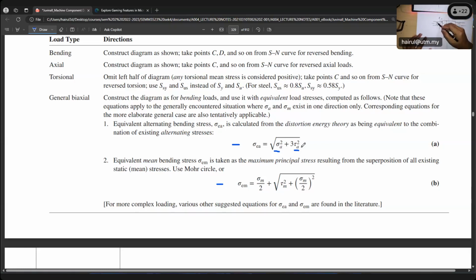Here we have a groove. What is the purpose of the groove? And what is the purpose of the shoulder? When you mount a pulley, can you watch my drawing, class? Can you see my live video? We mount the pulley at the shoulder. Why do we need a shoulder?